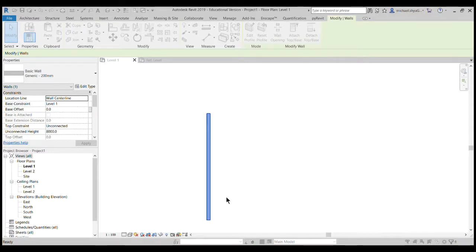In order to do that, you need to change the view. So go to View and go to Section. Now you can see what the wall looks like in a sectional view. After that's done, you want to go to Sweeps, and then you want to Add. Under Profile, you want to find your profile. So this is Feature Wall Profile. Click Apply, and there it is. It's all the way up.